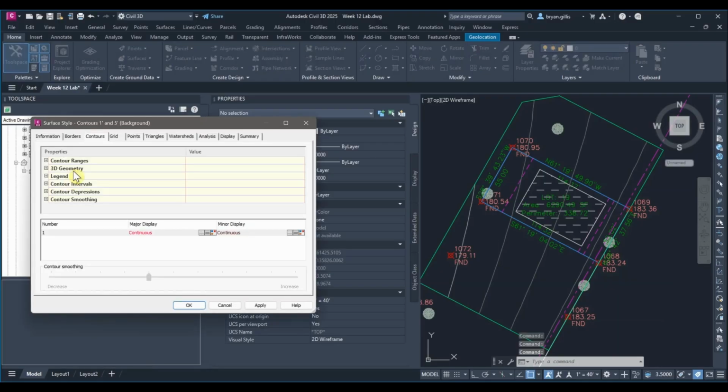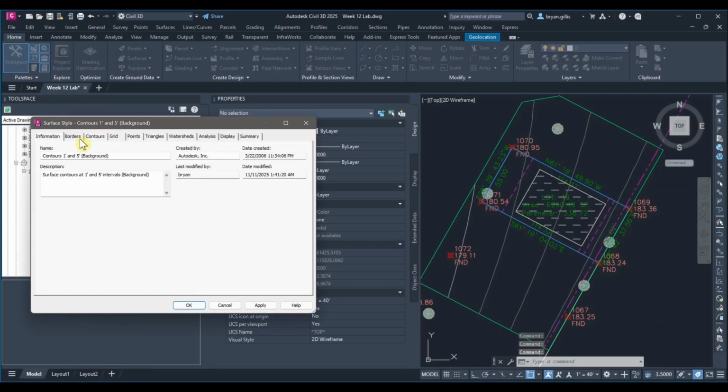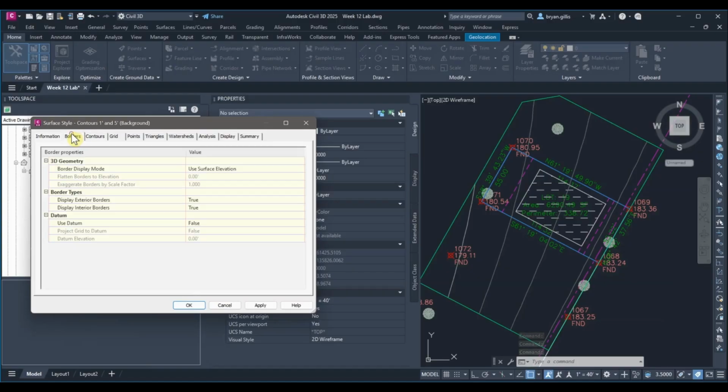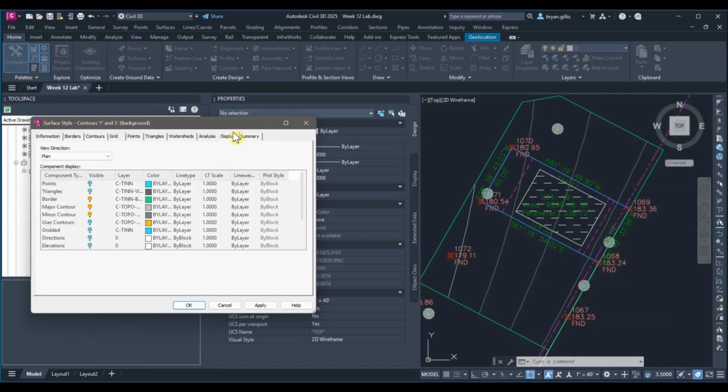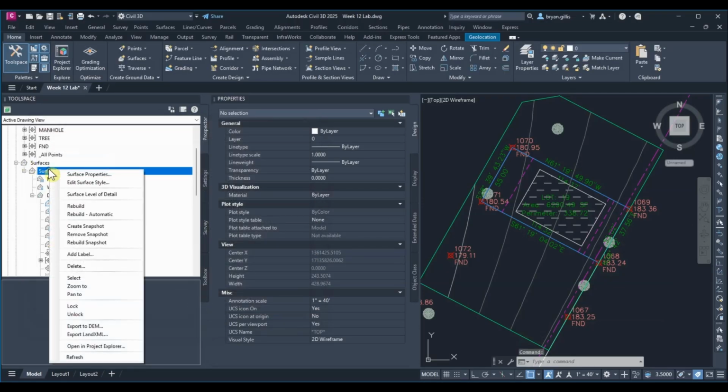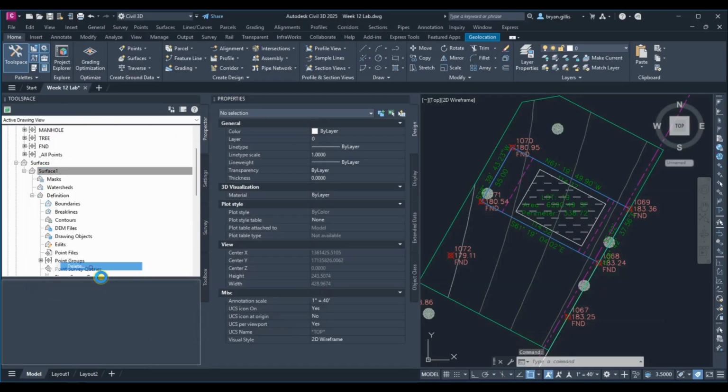So if we were to create a separate map just for the elevation certificate, maybe we'd put these contours on here. We'd denote the high and low points. We would denote the slope directions, as well as what the floodplain zone is for this specific area. I know from experience, it's Zone X. In case you weren't able to guess from the legal descriptions, I used to live here.